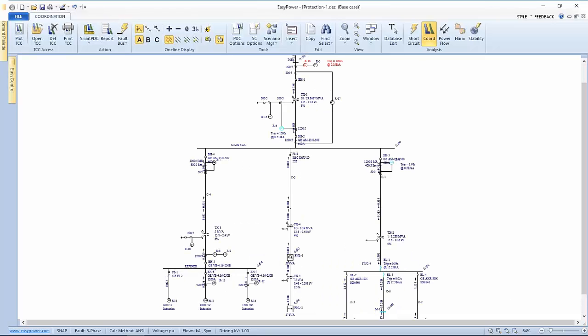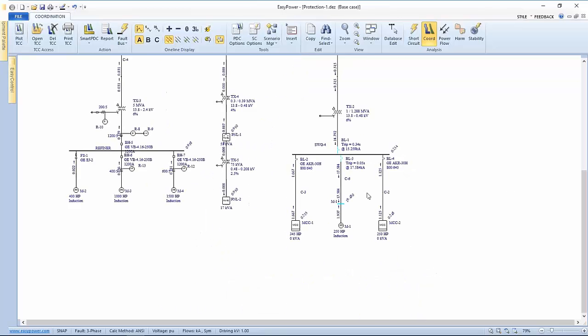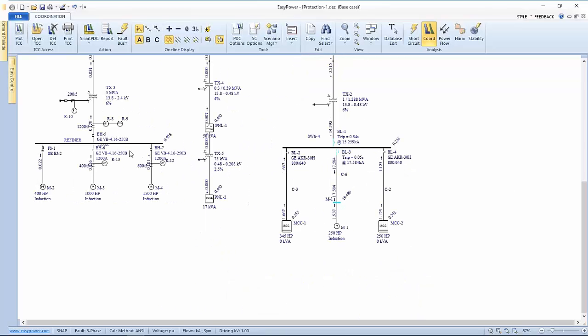And so now, based upon that one bus that we had selected faulting, this is showing me what the effect is on this bus over here. So if this motor faults, you'll see that the voltage on this bus, which normally is going to be 100%, drops to 0.9596 per unit.